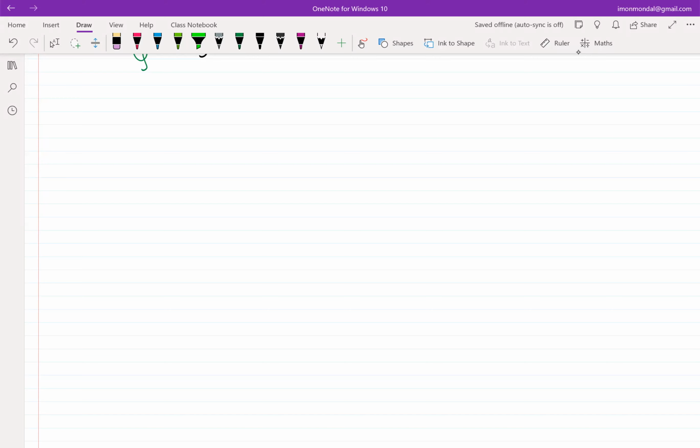In order to push the poles apart, I need a large capacitance because I have to split the poles. So how do I get a large capacitance? If you have not seen it before, it's slightly difficult to imagine, but once I tell you, it becomes very apparent. So let's assume you have a voltage controlled voltage source, right? Everything starts with that assumption, then we find that it's not possible, then we keep on changing. So let's assume we have a voltage controlled voltage source of gain -A. Okay.